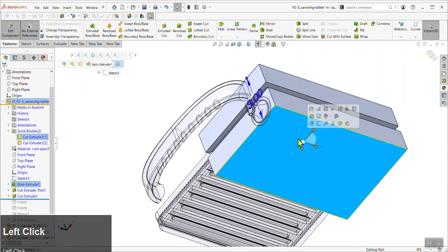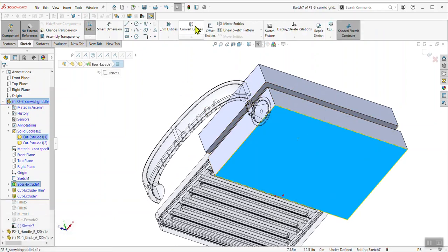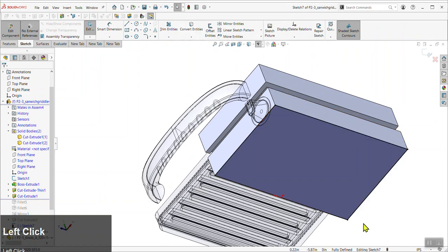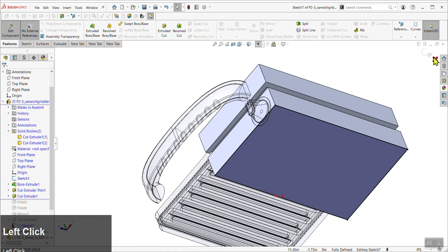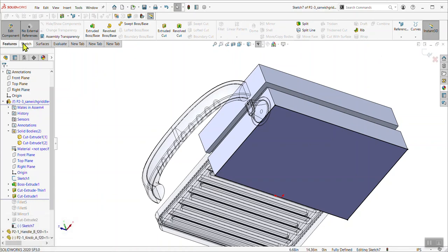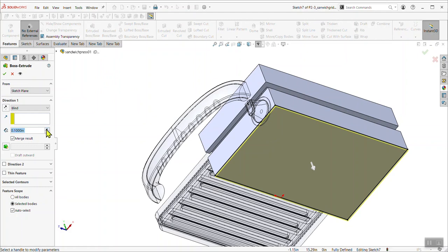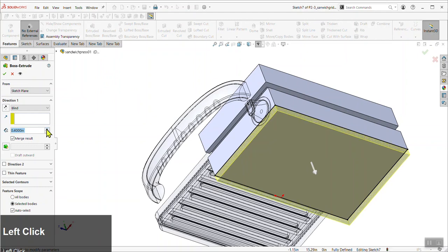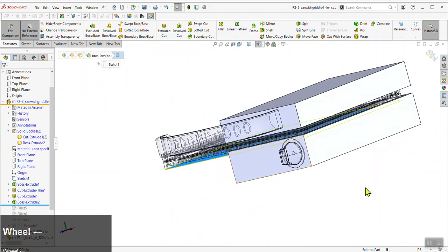So what I'll do is I'll select this face. I'll create a sketch on it by clicking Alt-S. I'll convert entities on the face, and it will just take all the outside edges. And you'll notice now that I'm in the Edit Part mode, we have some new tabs here. Pay attention. I'll call attention back to this when we exit. All these tabs will disappear, which is a good thing because it is possible to add feature commands in an assembly, but that is not good to do. It's confusing and it leads to file errors. So I'll emphasize that after this.